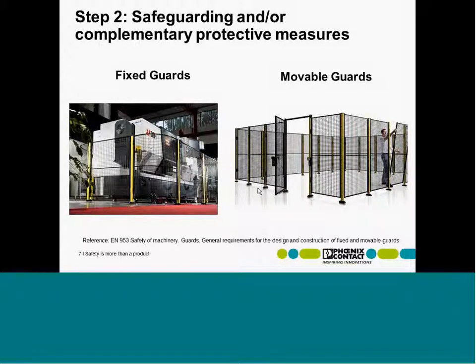An emergency stop device is an elementary part of the overall concept, but it's not a direct, primary risk reduction measure. So it's an important device, but the safety of a machine itself should be a higher priority than just an e-stop concept.